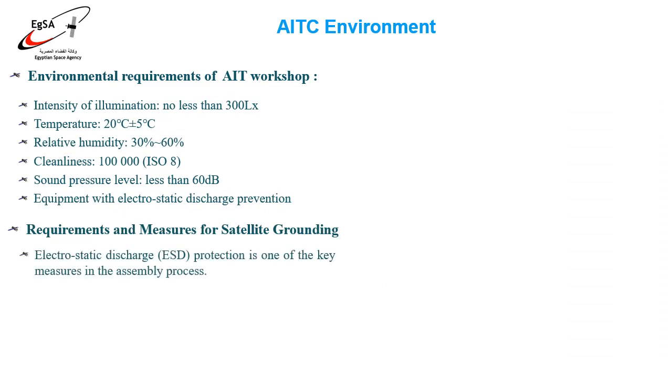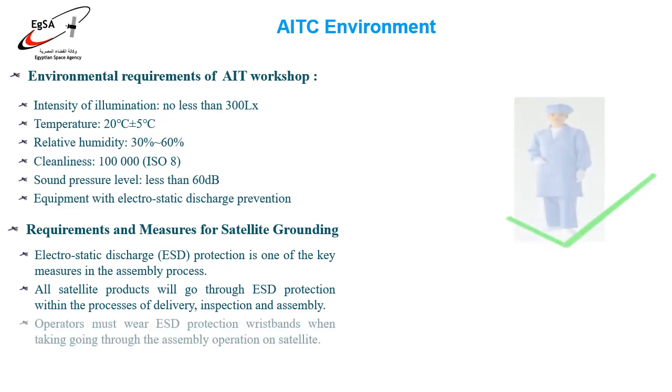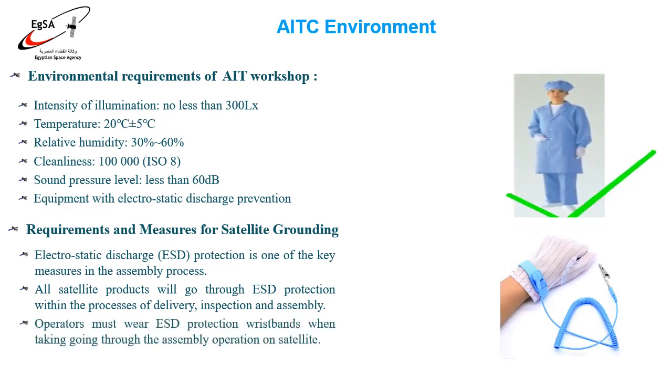Electrostatic discharge (ESD) protection is one of the key measures in the assembly process. All products will go through ESD protection within the process of delivery inspection and assembly. Operators must wear ESD protection wristbands when going through the assembly operation on the satellite.